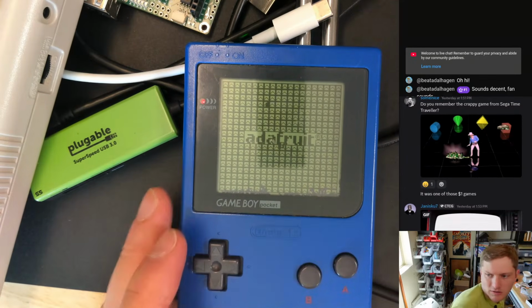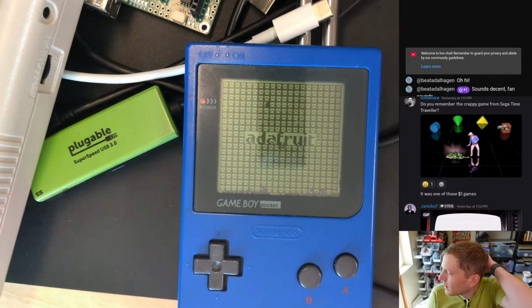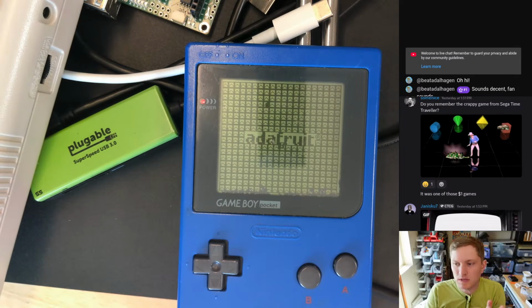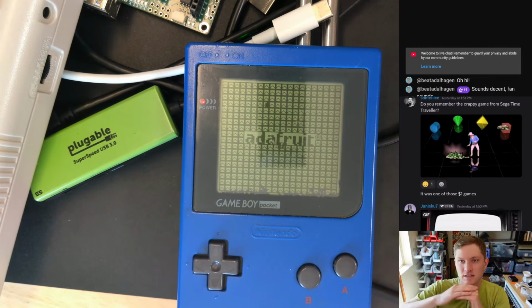And this is all happening during the VSync or the VBlank interrupt. The Game Boy should be halting at the end of every frame. It waits for a VBlank interrupt, then jumps to the VBlank interrupt that it loads from CircuitPython. CircuitPython has a number of commands that need to be queued up.